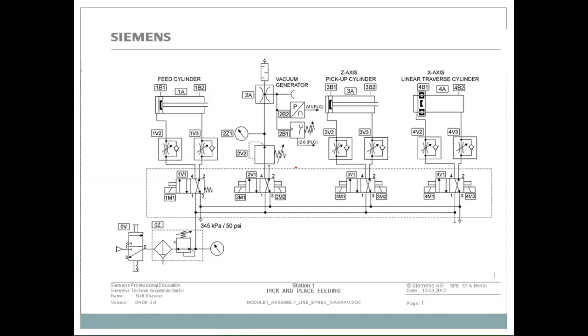So what I'm looking at here is what is called meter out. Because when I apply pressure, it's going to go through the check valve. But what I'm controlling is what's coming out of my cylinder, because it can't go through that check valve. Instead, I let it out very slowly, so the pressure takes more time to push that cylinder back, because it's fighting the pressure of the cylinder emptying. Does that make sense?